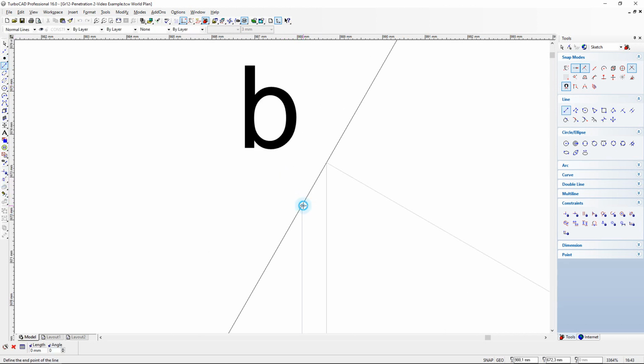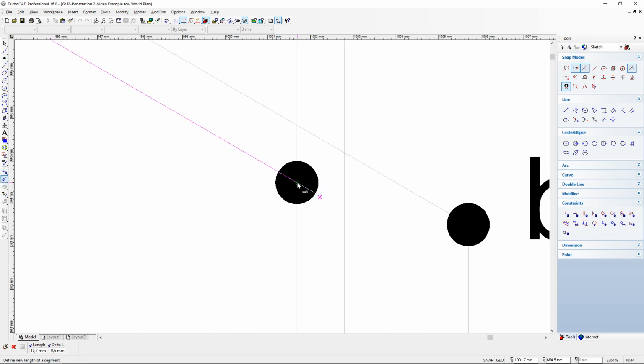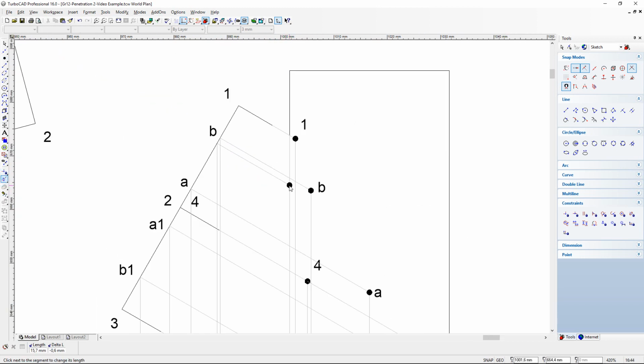And then from that edge I'm going to go once again like before, go backwards and obviously it will only be to here to the edge of the cylinder. So I need to go and just make sure that it is at an angle of 330 degrees, and then I draw that construction line, and that is exactly where the depth of that will be. I just want to once again quickly draw that line right to the intersection.